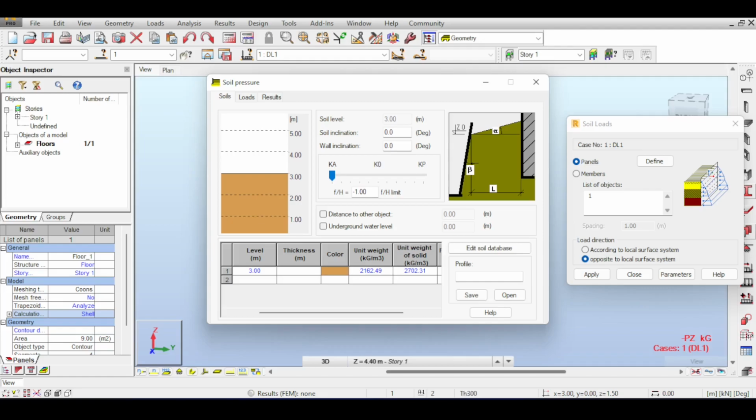And the difference here being where the unit weight here is the bulk unit weight, where the voids and compaction ratio do have an effect, meaning that if you have higher compaction to the soil, the unit weight increases. If you have lower, the unit weight decreases. The unit weight of solid is basically the unit weight of the stone pebbles themselves. The friction angle is, well, as the name suggests, the friction angle of the soil. Of course, you can choose other soils, for example, clay and stuff like that, and now you have anything you want. I'll just say my own soil basically, and I'll change the friction angle to 23, for example. 23, not 300. And you can choose anything you want here.